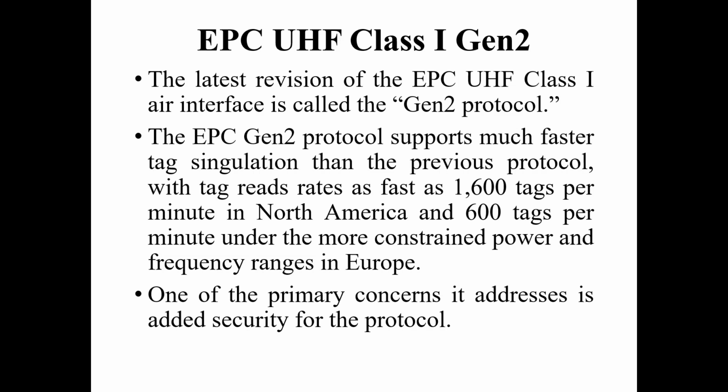Then comes anti-collision, it is purely singulation using slotted Aloha. Then tag memory banks can be categorized into reserved, EPC and user memory. And the tag commands are inventory commands, access commands and security commands, based on different applications.